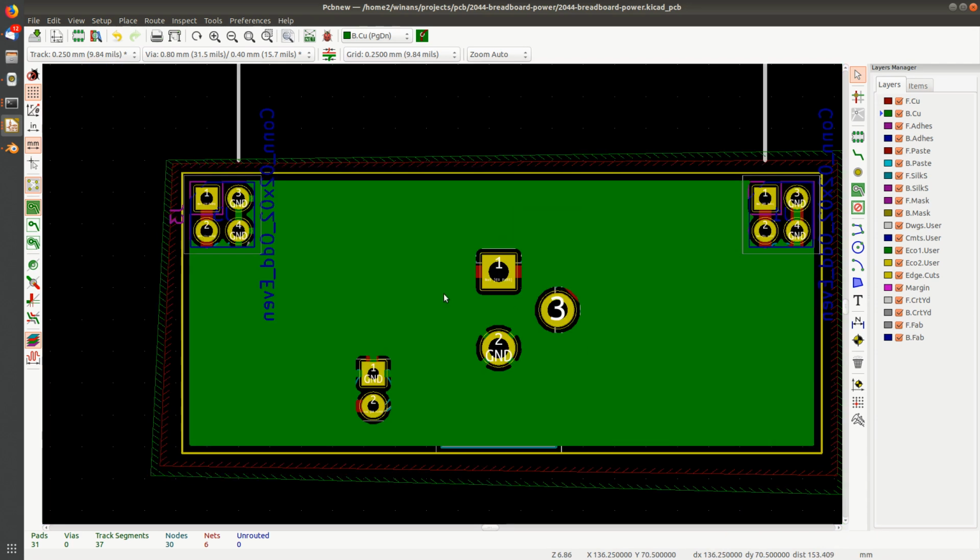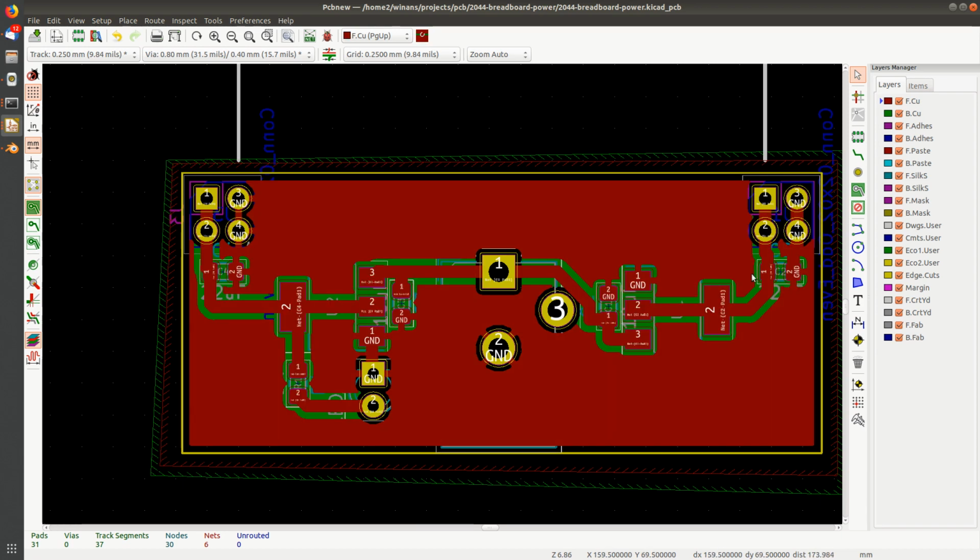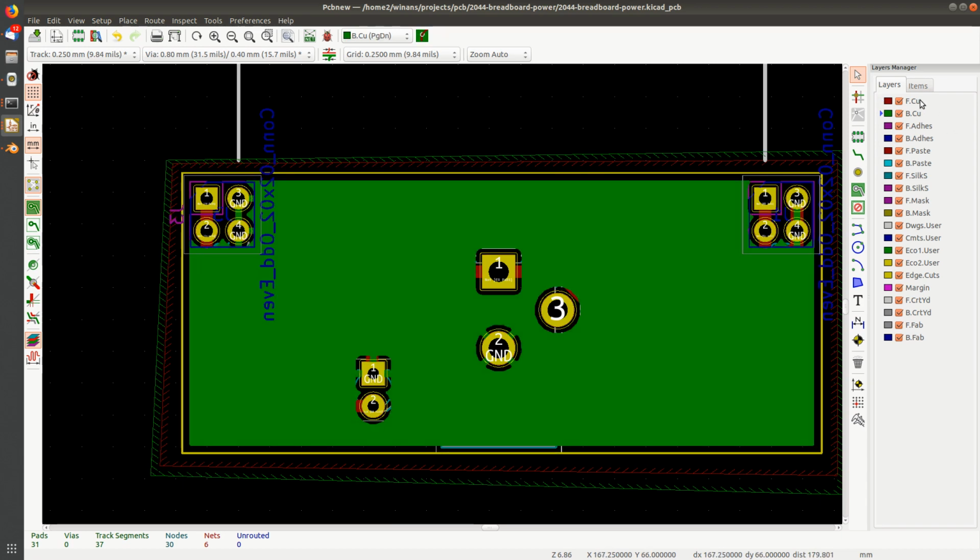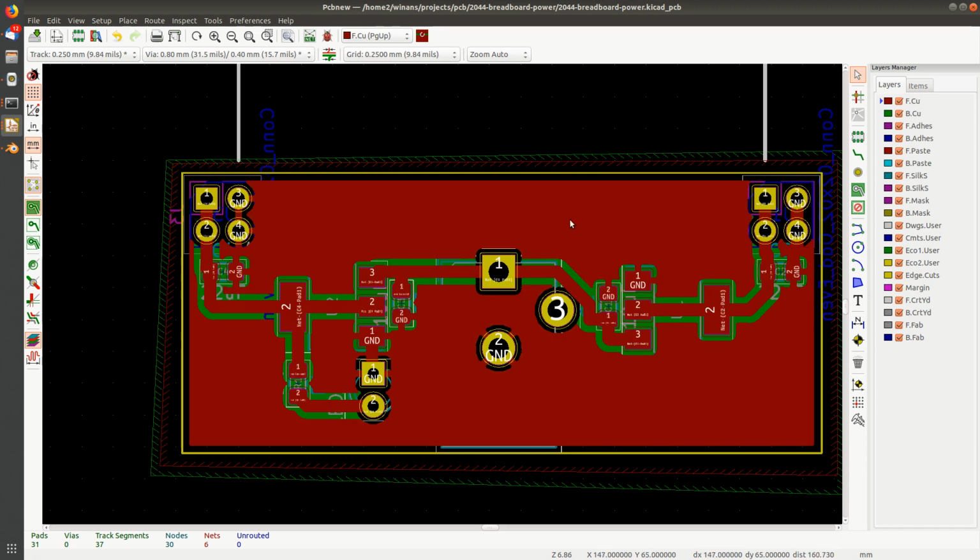The back, since there's no horizontal lines anywhere, the ground does connect up and around to these pins. So if we then go back to the front and we look at the back, you know, there's no more air wire. Why? Because this ground-filled region here is connected to ground through this pin. This pin connects the back everywhere and the front down here. Okay?